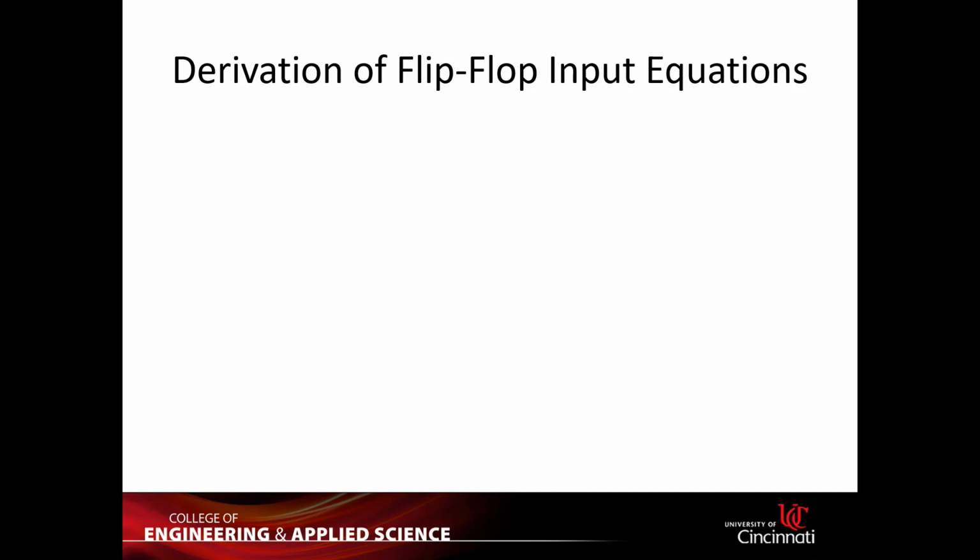And finally, you need to learn how to derive your flip-flop input equations. From the state table, you have to get an equation for the input of each flip-flop.